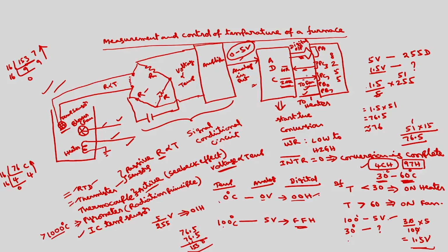So what is the control register for this? If you want the control register in I/O mode, this is for port C lower. Port C lower we are using as an output port, so this will be 0. This is port B. Port B also, you are using these two pins as output, so 0. This is the mode selection for port B. I am using mode 0.